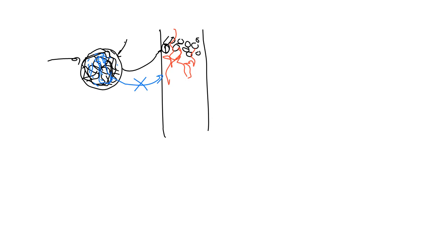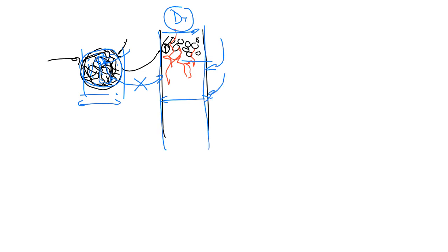The area in here does not affect this, because we assume steady state. We assume that the heat transfer is sufficient. I choose my heuristic so that my tube diameter is small enough that I neglect any radial temperature differences. That is what I must ensure. And if I don't have any radial temperature differences, I don't have any temperature profile differences over the diameter of my catalyst particles. So the area for heat transfer is only to do with that piece of steel that is there, with or without the catalyst present in my reactor. The catalyst affects the flow path and the velocities that may affect the h values, the heat transfer coefficient values, and that's only the bed porosity and not the porosity of your catalyst particles.